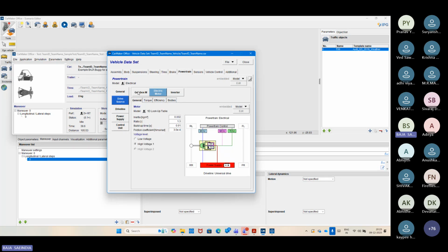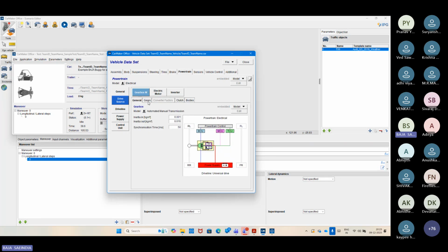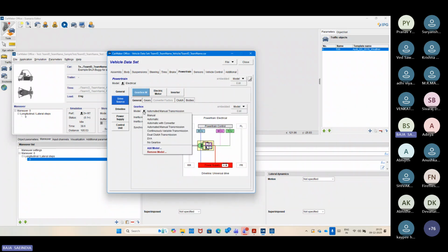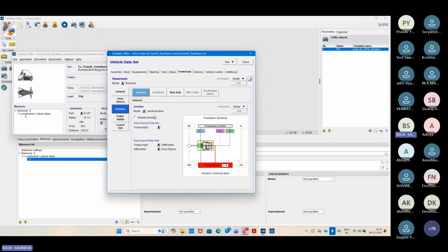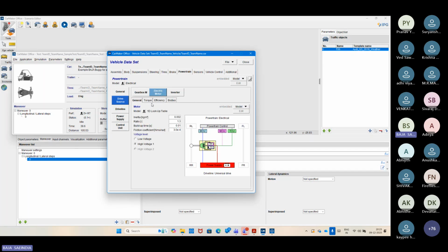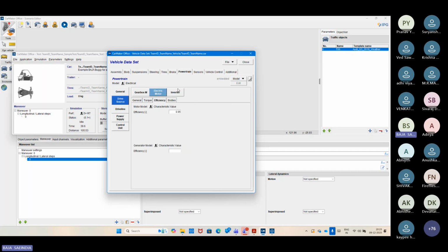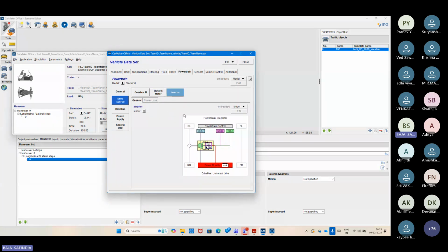You can refer to my yesterday's session on this in detail. If your motor is mounted directly with the gearbox, you need to select it as no gearbox and then mention all the things over the driveline. In the electric motors, you need to mention your motor torques and efficiencies. Then after, inverters you can skip if you do not have regenerative braking.